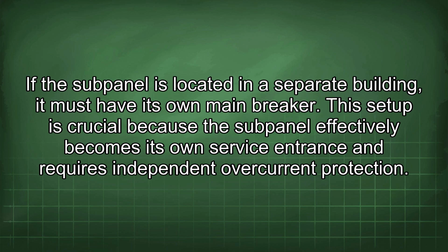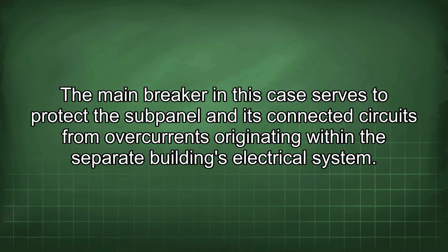This setup is crucial because the subpanel effectively becomes its own service entrance and requires independent overcurrent protection. The main breaker in this case serves to protect the subpanel and its connected circuits from overcurrents originating within the separate building's electrical system.